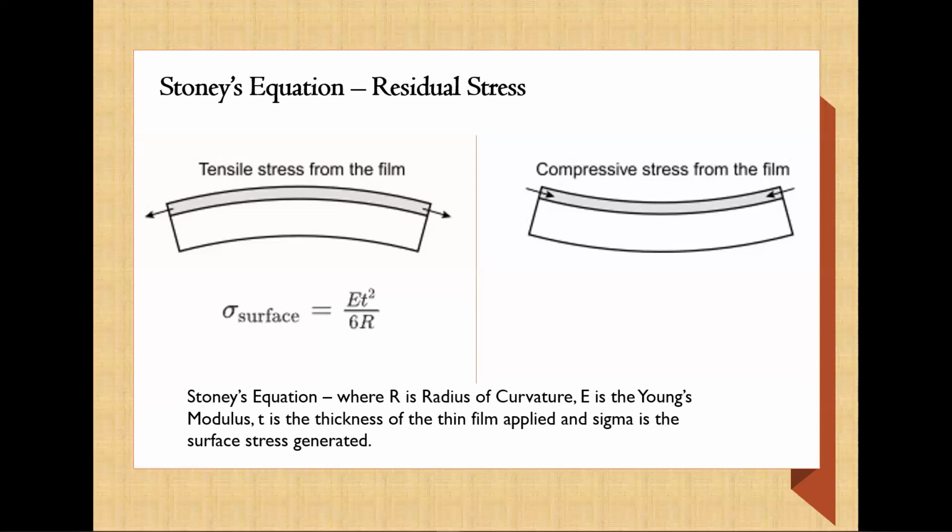So we either want to measure this in situ or post deposition. In situ being during the deposition process, we could figure out a way to measure that. A recent study done was using a deflection of an optical beam, and they were able to measure the curvature of the surface during the process, which could give us applications for the stress gradient rather than just having a pure tensile or compressive on the surface here.